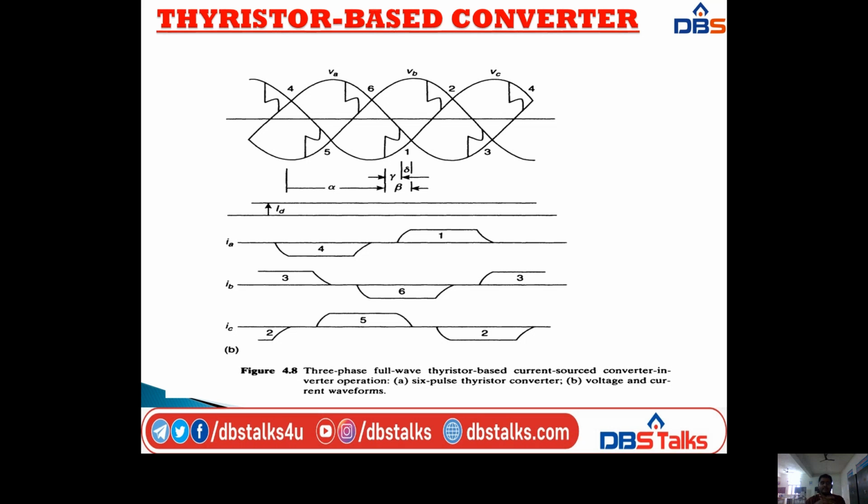So here also I am taking the first waveform. It takes the voltage waveforms for the 3 phases A, B and C. Next we have the DC current waveforms and phase currents IA, IB, IC waveforms. Here we are using the 3 angles gamma, beta, delta. So these are the waveforms for the 3-phase fully thyristor-based converter, meaning the current source converter in the inverter operation.